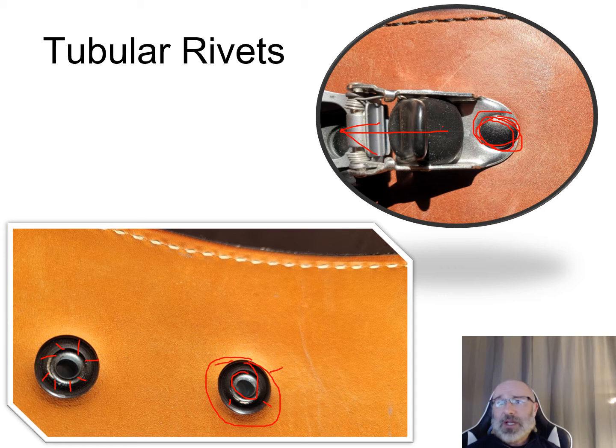So that's what I did, is I put these on an MTS machine with something that expanded radially to put pressure on them as it would in a real life situation. And with that, I was able to take a look and see when certain rivets would pop, when other ones weren't, and where the failure would lie within this here. So what I found is going up to 1,000 pounds on a testing machine, the leather would stretch before anything would pop out or get destroyed. So these rivets held up for over an inch of deformation as we're expanding outwards with the leather. So these ended up being the best rivets, whereas if I went with the double rivets or the rapid rivets, they would actually pop under these tensions.